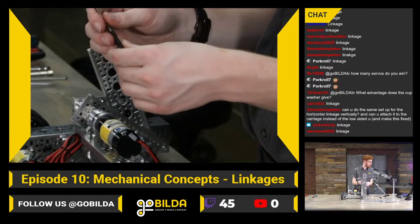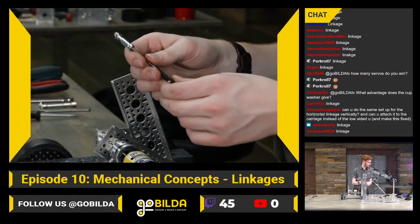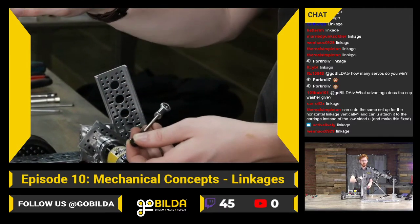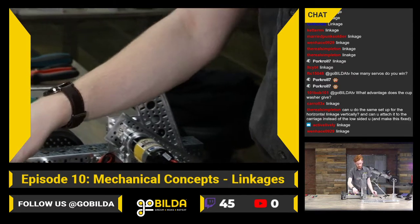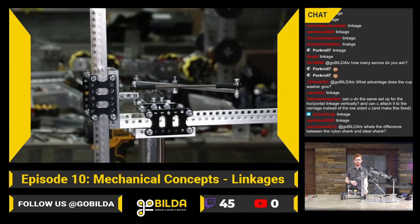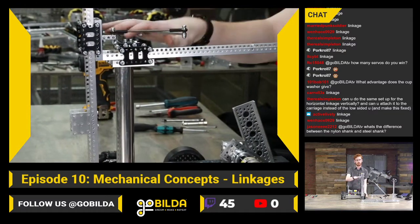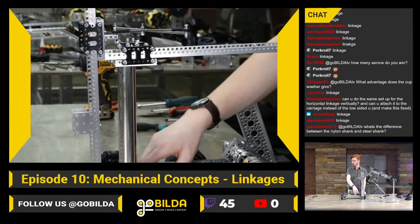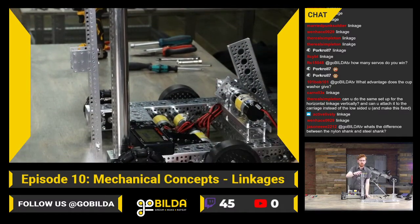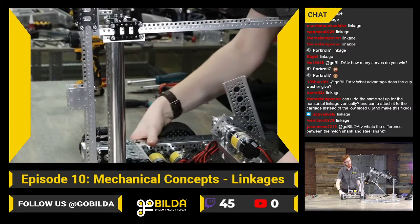Can you do the same setup for the horizontal linkage vertically? Can you attach the carriage instead of the low side and make this fixed? You definitely can, and that's actually what we did pretty much right here. I forgot the servo was on, where the carriage is stationary and the low side U channel is moving, and you can absolutely rig this up with a very similar linkage. You likely would want to use something like a torque servo so you get a little more power out of it, but something like this would work really, really well with a linkage vertically.